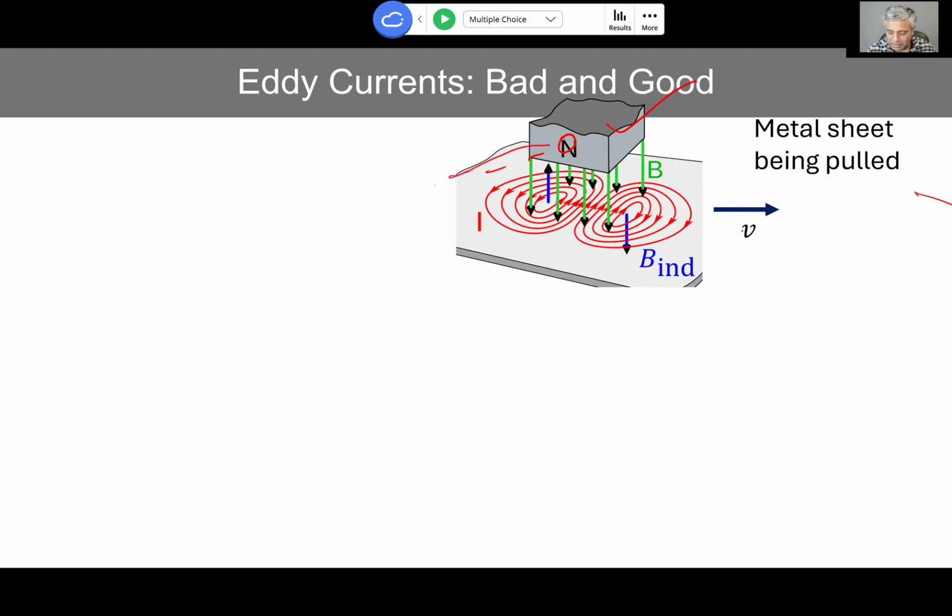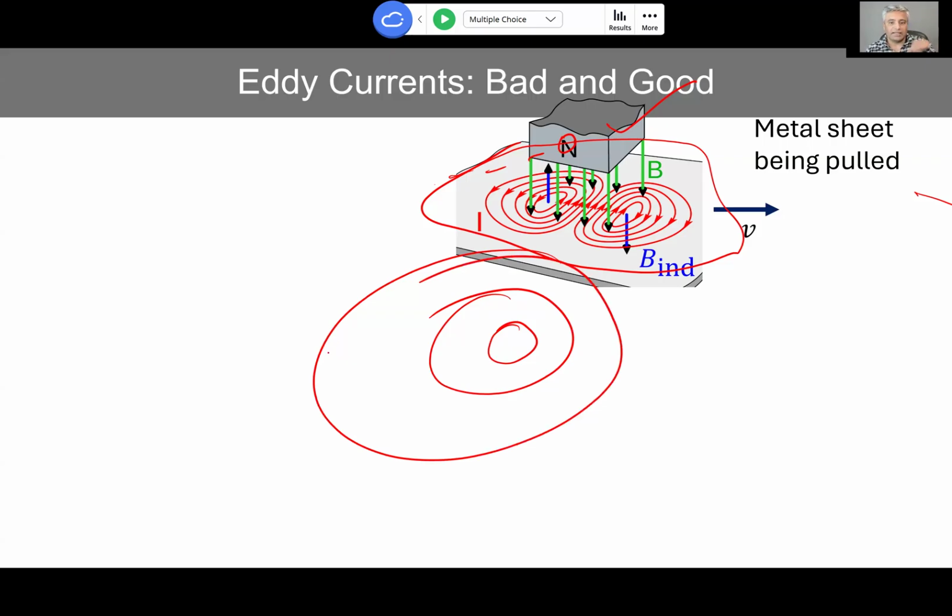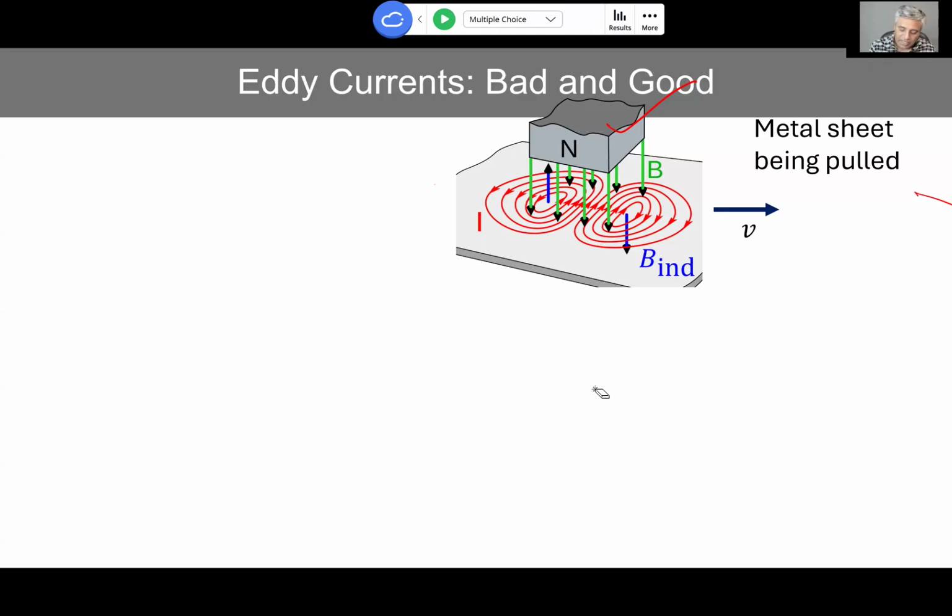So see, this is a metal plate, but we can think of it as made up of a lot of coils, for example. The current can circulate here because there is no broken path. So current can start circulating there. So what happens is this changing flux induces current here. And if we were to use Lenz's law, we can tell which way the current is going to be circulating. So in this case, the original magnetic field is in that direction, is step 1. And then since it is going that way, means flux is increasing. So to oppose that, it has to be developing field in the opposite direction. So that's why the induced is given by this blue color. Original fields are drawn by green colors here, and the induced is drawn by blue color here on this side.